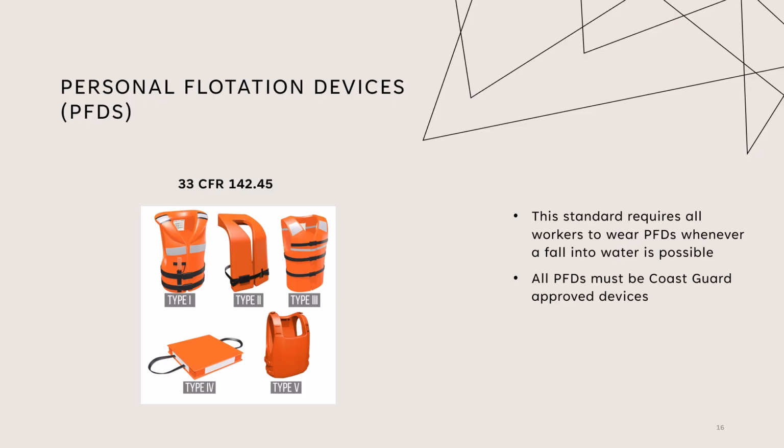Next up is 33 CFR 142.45, personal flotation devices, PFDs for short. This standard requires all workers to wear PFDs whenever a fall into water is possible. All PFDs must be Coast Guard approved devices.